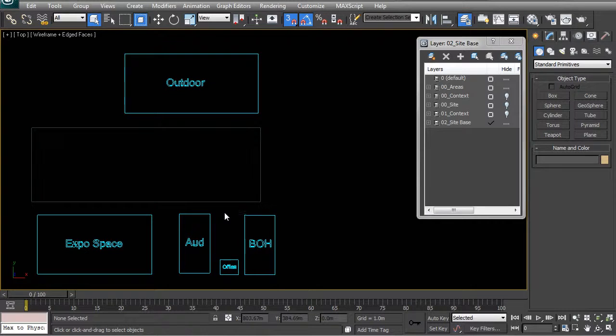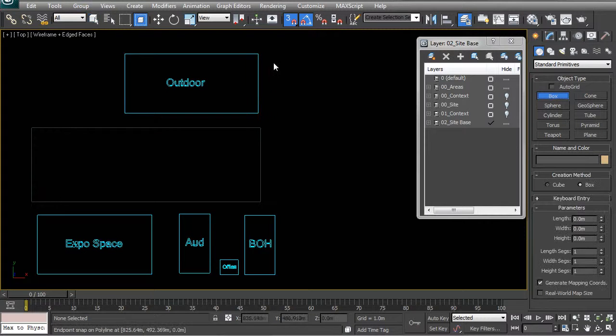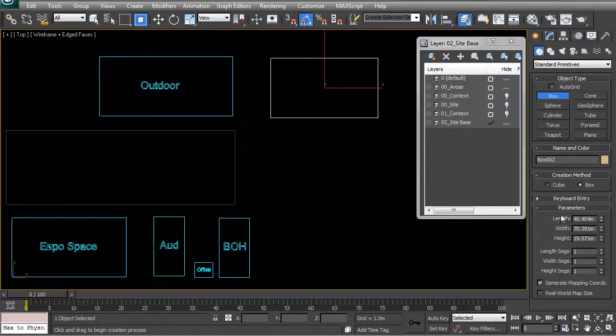And I do just want to make a note here that you could very easily go and start the entire area process by just drawing out blocks in 3D Max and then just manually typing in the length, width, and height of them. The reason why I wanted to include that AutoCAD step, even though it is a little bit redundant or not necessary, is because if you do have pre-existing AutoCAD elements, for example, a lobby that has already been drawn up from another project, perhaps a stairwell, then perhaps you want to go and take the areas just as a single outline of those elements and then bring those into 3D Max and keep them as fixed objects. So very often it's nice to work in conjunction between the two programs as you develop your building.